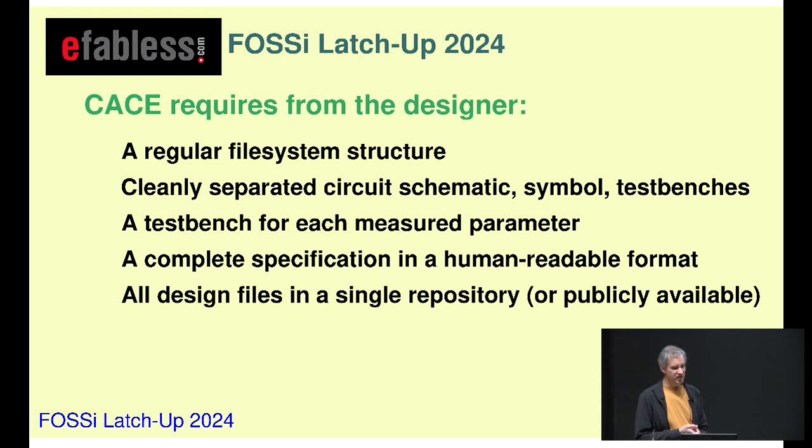You need to have a test bench for each of the measured parameters, although you can reuse a test bench for different parameters. And you need that file, which is the complete specification of the circuit in a human-readable format. And then all the design files need to be in a single repository, or else if you are reusing parts of your circuit from another public repository, you need to declare those, and the tool needs to be able to find them and download them.